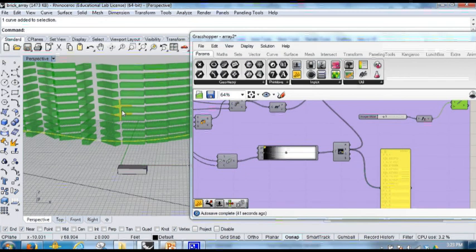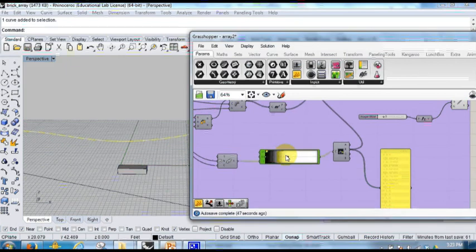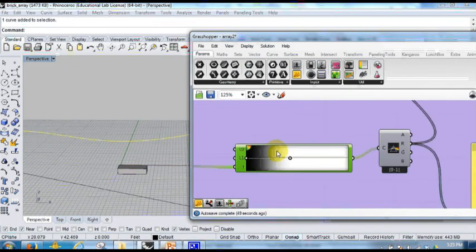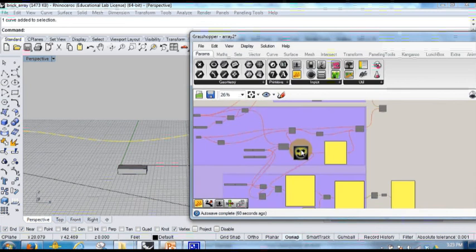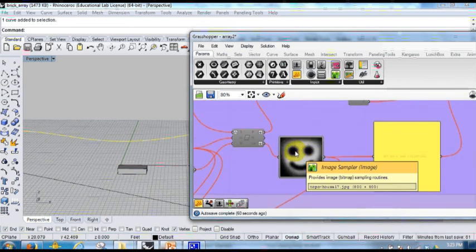All right? Not just manually do it. I want to use a color. So instead of using the gradient, which is, I would say, a one-dimension line, right, from dark to bright, in this case, if I want to do a 2-dimension control, I should be using this new guy, the image sampler, which will give me the information on a 2-dimension surface.